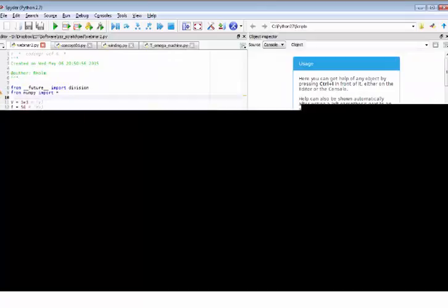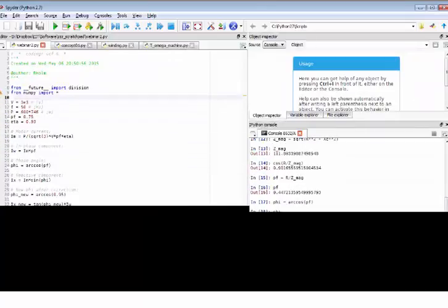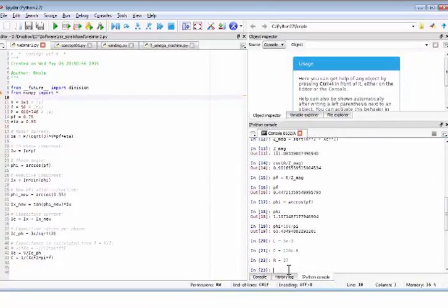Okay, so you can see here in lines 20, 21, 22, I have defined L, C, and R. We use the E operator to indicate times 10. So 5 millihenry we indicate by 5 times 10 to the minus 3 Henry, right? And C would be 120 microfarad, indicated that way.